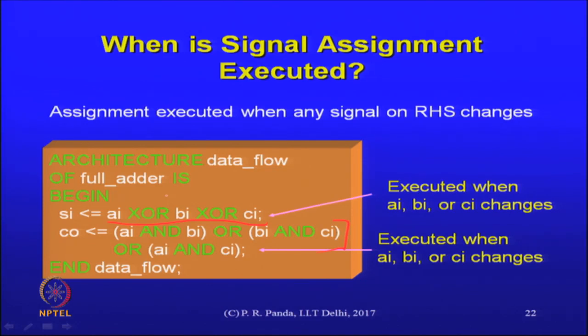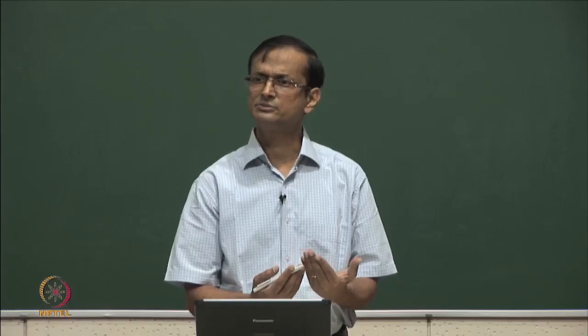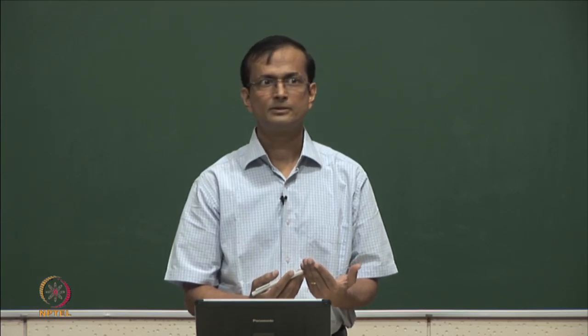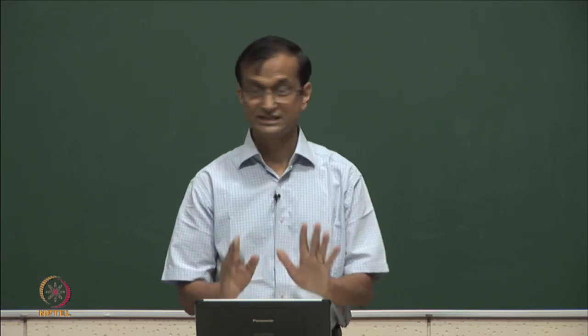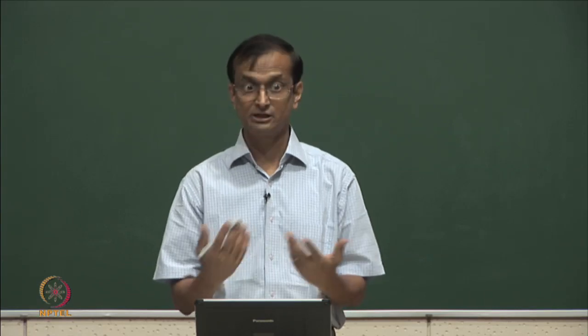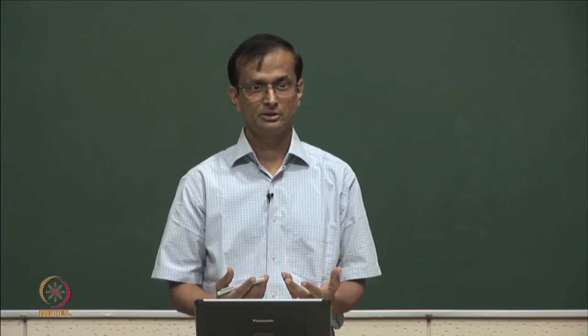But does it make sense to have a rule like this? The consequence of this is that if those inputs did not change, then we will not re-evaluate the output. Not re-evaluate means the output retains whatever was the last computed value for the output. Does that make sense? Why does it make sense? Is it correct first of all according to the way we think about the hardware design? It is correct.